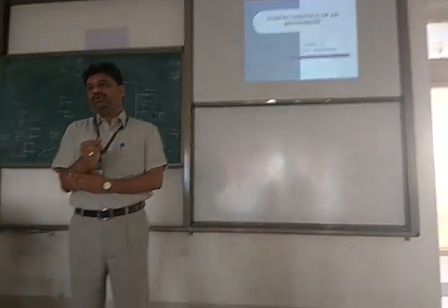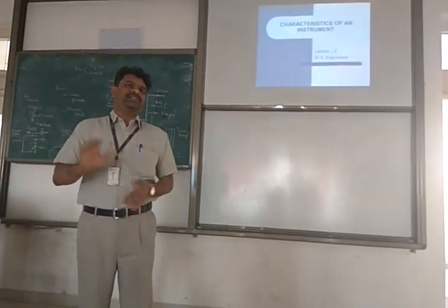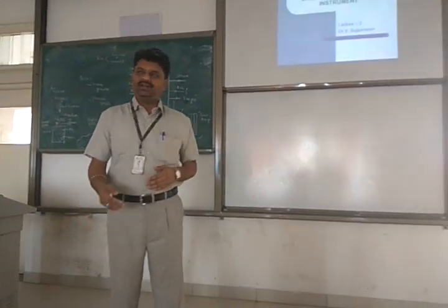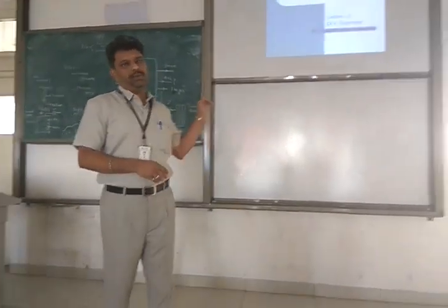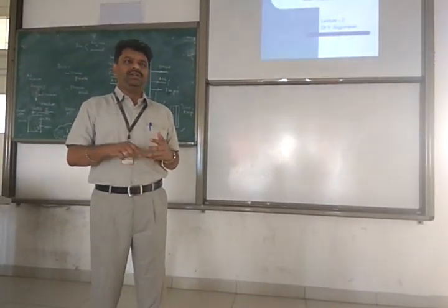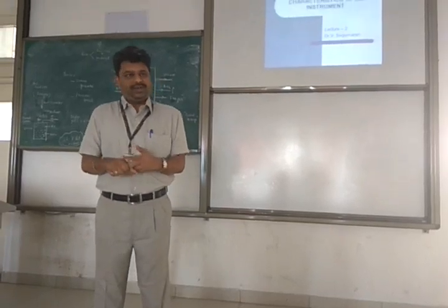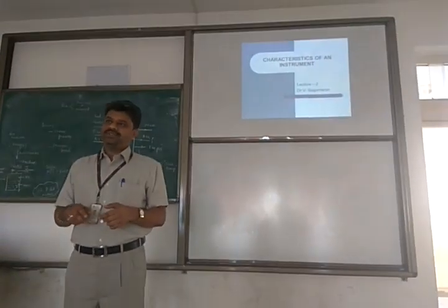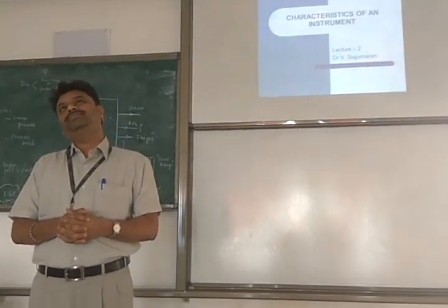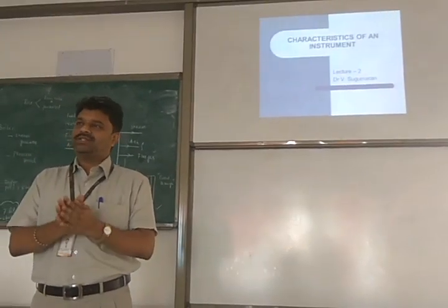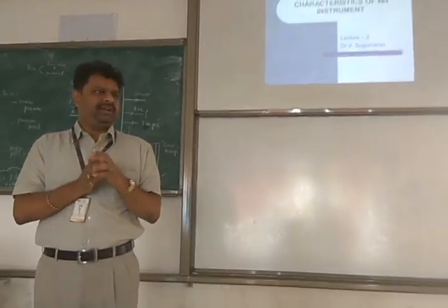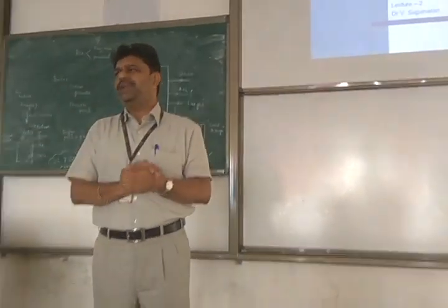Different terminologies used to describe the characteristics of instruments. Today, and probably another 2 classes, we will be talking about this topic. There are a variety of terms, starting from accuracy, precision, repeatability, reproducibility, sensitivity, range, frequency response, resolution, least count, like that. More than 20 terms are there.